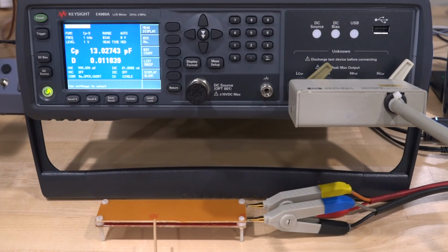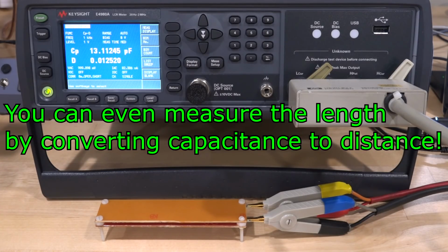So let's try that. Here we go. So we're sitting at 13 picofarad roughly. Push this in the middle. Look at that, 13.15, just simply by that tiny piece of wood. If I remove it, okay, it goes back to normal. It's really quite amazing that you can measure the effect of something like this.